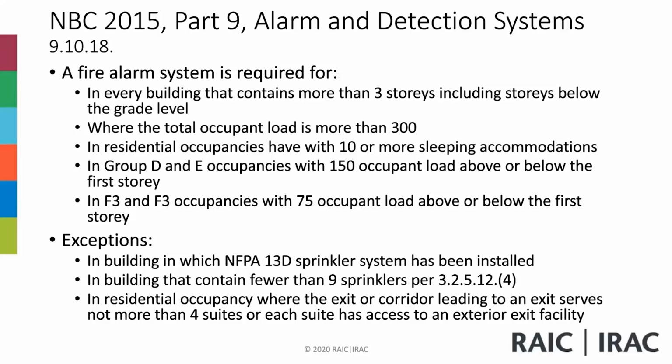No question there? Okay. So just to be clear, if you have a 3-story building plus a basement, that's when the fire alarm kicks in. Where the total occupant load is more than 300. Okay. Where the residential occupancies have 10 or more sleeping accommodations.